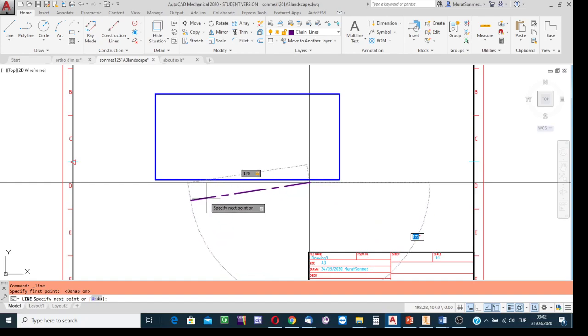From the arc simulation, I see that AutoCAD is ready to measure the angle in the clockwise direction as equal to 180. Write 180 degrees into the box and press the enter key. That is it. Press the escape button thereafter.